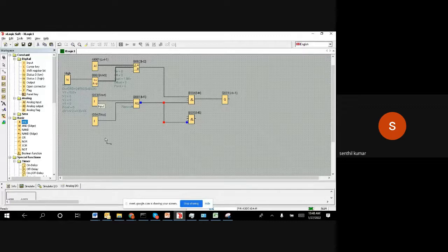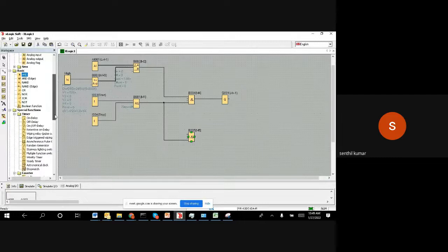You gave a main start, the green button you pushed, but in case you push the red button, it will go off. So that is a must in the AND gate. As you know, in an AND gate all inputs should be one in order to proceed. So one condition is that it should have been started, and the first valve should have been closed. So we need to make a NOT gate, because this can close only when the level is less than 500. After that, we want to open the valve. So I want to put a NOT gate here.